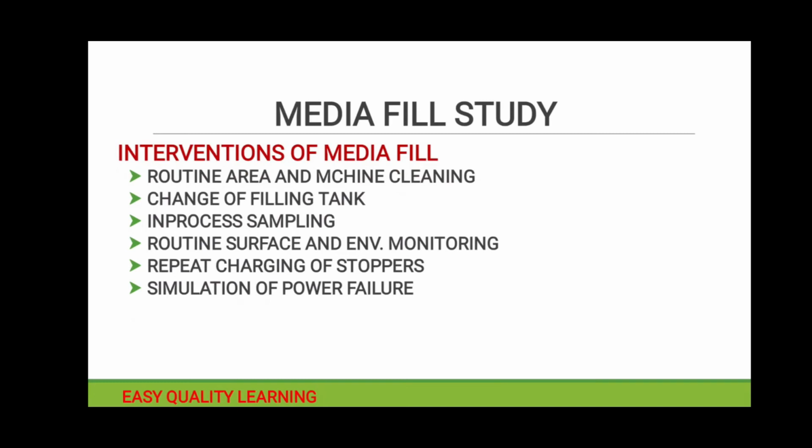Change of filling tanks. It might be possible that we are filling 5,000 or 10,000 vials, so one tank will be sufficient to fill 5,000 or 10,000 vials. But in our routine batches, the maximum batch size is 200 liters or 500 liters, so multiple tanks are utilized for filling of the complete batch. So whatever number of filling tank changes there are, if it is 4 changes or 5 changes, those need to be simulated during your media fill activity.